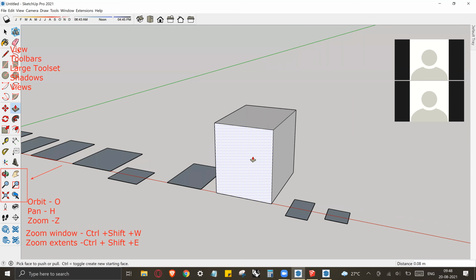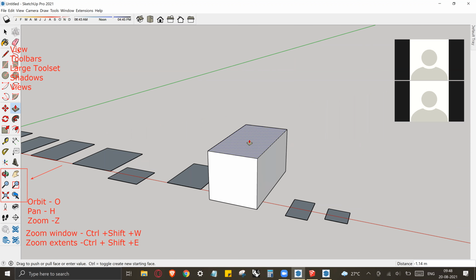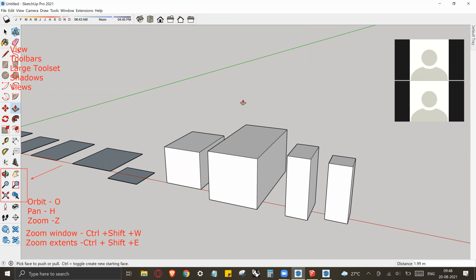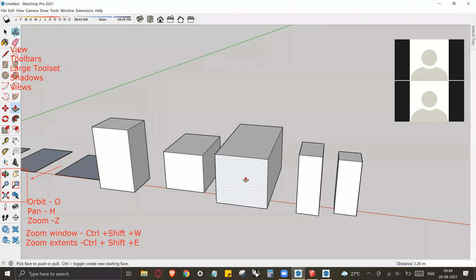This way, guys, every single surface you can push or pull like this. Now, as I mentioned, we're going to go in depth into this particular tool in the coming classes. But just for today, you can pull up some surfaces that you have made, just using the letter P to bring up the push pull tool, click, drag, and then click one more time to stop. Now you see we've got a couple of boxes like this, right?